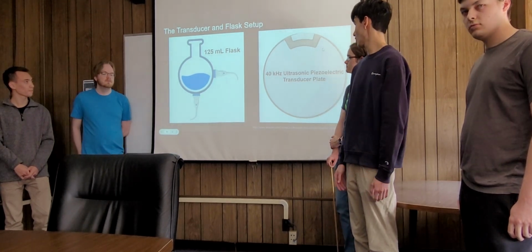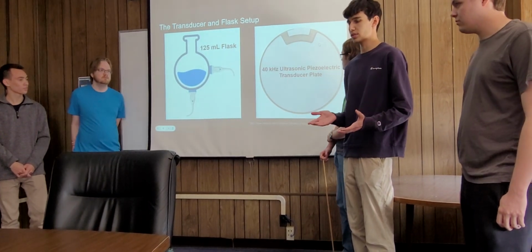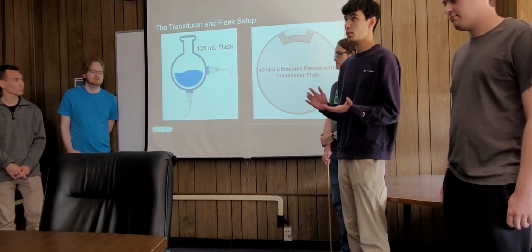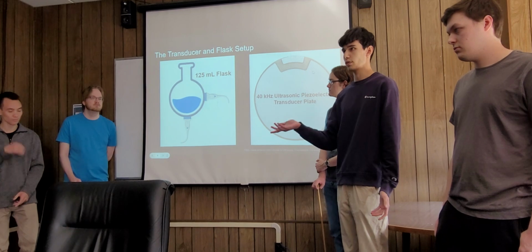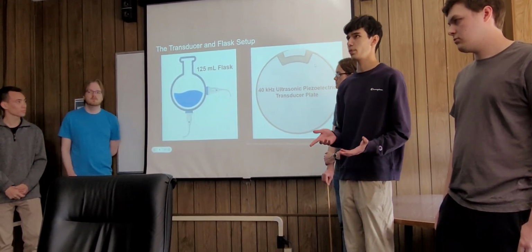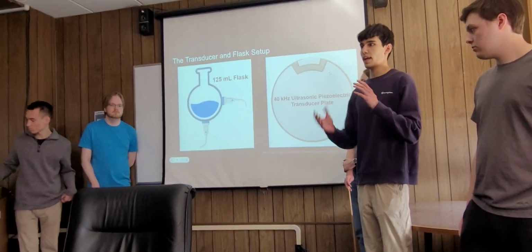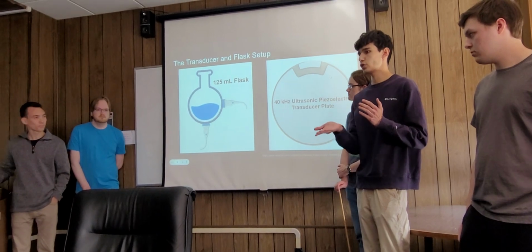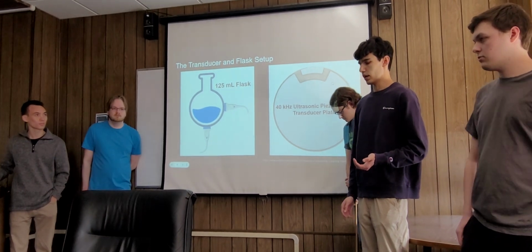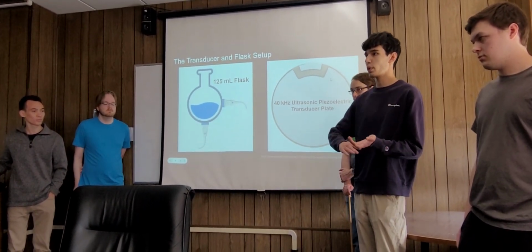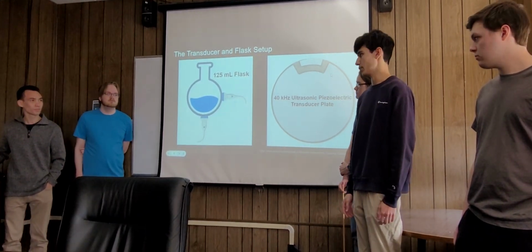One way is by using something called, as previously mentioned, an ultrasonic acoustic transducer, and that's just a fancy word for something that converts or transduces or transforms electrical energy into acoustic energy. So it's just like a speaker that's operating at the ultrasonic frequency range. And I'll get into why we need that in a second. But then all we do is we have a flask full of water, and we can attach the transducer to the bottom of this. And then whenever we drive the transducer at some frequency, it will send corresponding pressure waves through the actual flask itself, and that can cause the cavitation to happen.